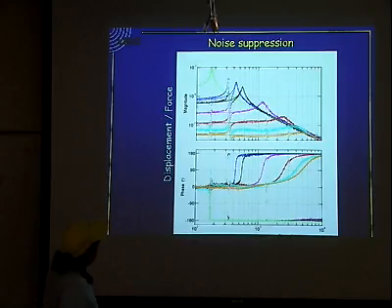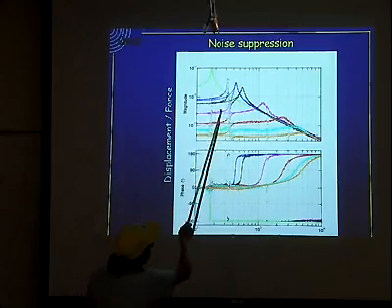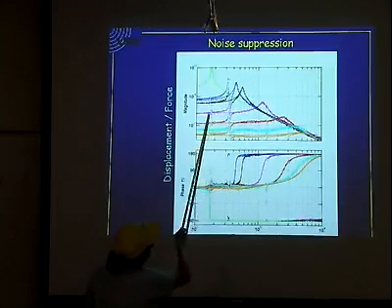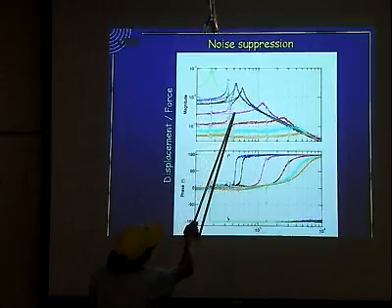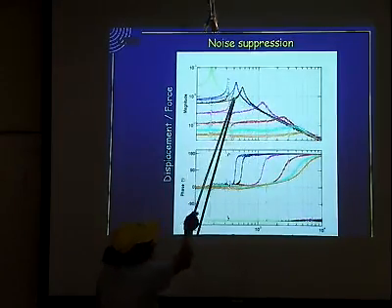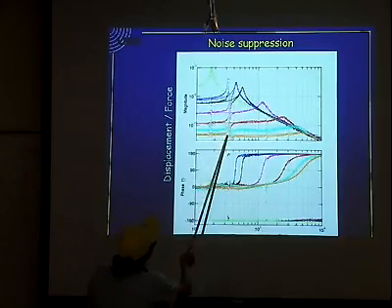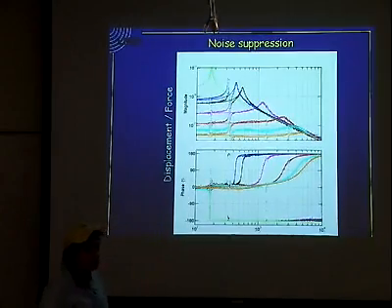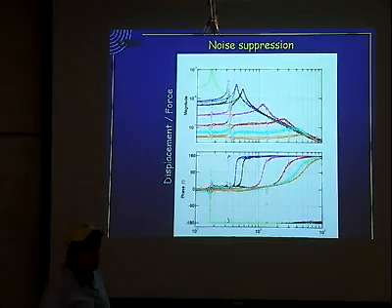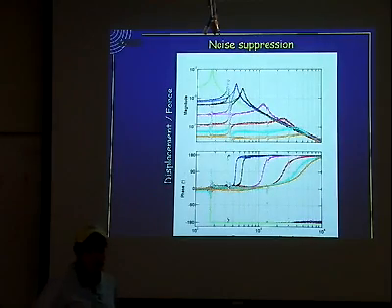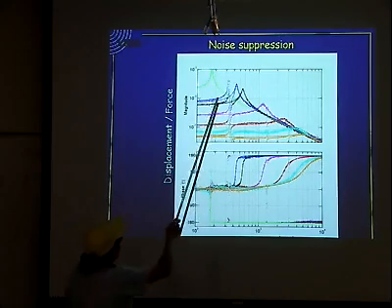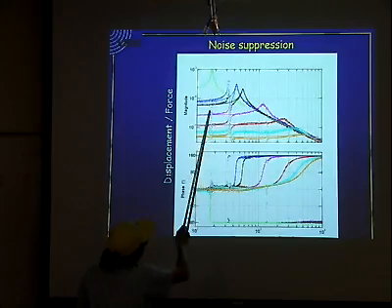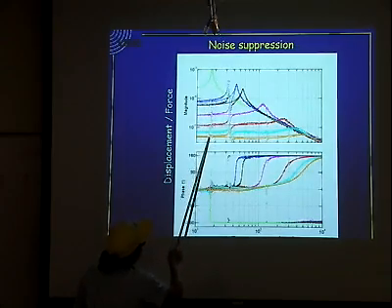And what you see, and I should point out that the dotted curves are data, but there's a fit from that Simulink model that's the solid curve, and you can't really see the differences except right over here at 350 hertz we have a spurious mode. It's the pitch mode of that little object that we don't control, and it's not in our model, so we don't model it. But other than that, what you see is the optical spring starts at 170 hertz, and you can see a little bit of dirt in our data from that.